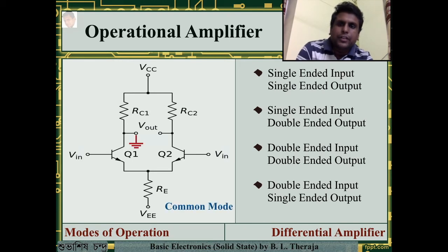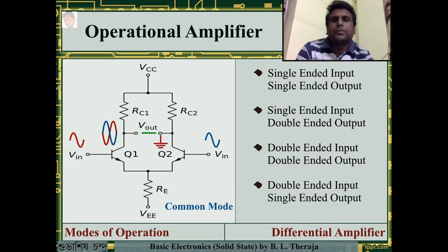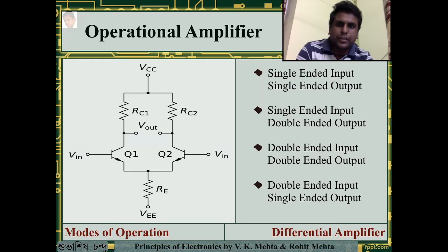For the common mode signal, again we do the drill. We see we don't receive any output again. We check with the second output terminal and we do the drill again and we receive no output again. So a double-ended input, single-ended output differential amplifier also rejects the common mode signal. Let us see what it does with the differential mode signal.